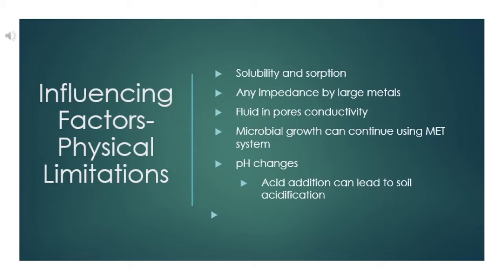To combat this, a length of tube filled with solution can be placed between the cathode and the soil, where the heavy metals can then precipitate into the water rather than into the soil. Another way to prevent the metals from precipitating into the soil could involve introducing a cation selective membrane to be placed in front of the cathode to stop the advancement of the hydroxyl front toward the anode. This process can considerably decrease the amount of water volume needed, while still ensuring the low pH conditions for the soil that is being treated.